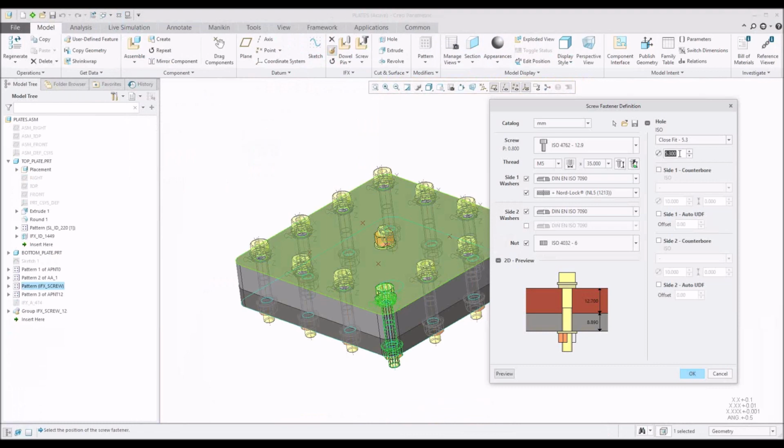As soon as you start designing with a top-down approach and make changes where it's not driven from the top assembly, you're going to lose that link somewhere. The only way to pick it up is if you actually look at the model tree of a component and see that particular hole was changed. So my answer is yes, you can. Is it a good idea? No. Rather drive it from the top assembly where you created that hole.